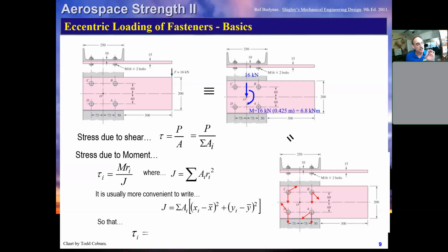What we're going to do first is focus on our total stress, which is just P over A of each plus or minus the M R over J. But notice here, this is the little vector addition sign. We can't just add those together, take a root mean squared. We need to put them together using vector addition. And we're going to learn a better way to do this.